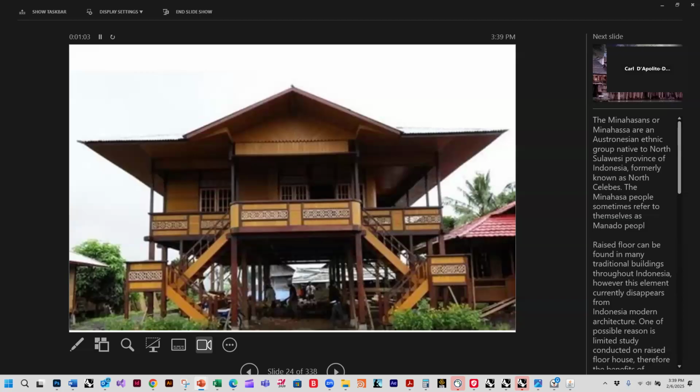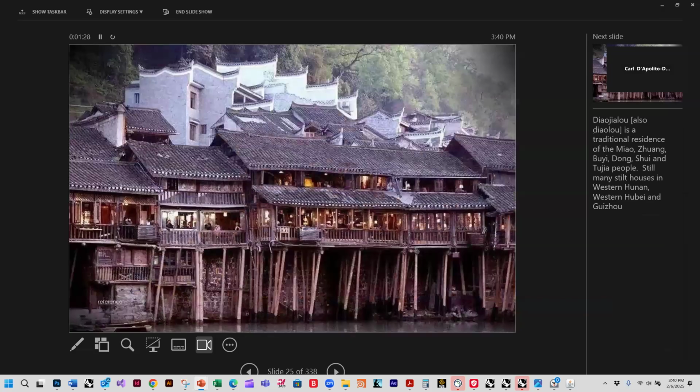You end up with cold air going under below, and then there are holes in the floor. Since the air is moving faster down here than here, and this is colder than in the house, that creates movement of air into the house, and then the hot air in the house rises, and there's a vent up here, and it shoots out. So essentially, the temperature difference and the movement of air contribute to each other and help each other out.